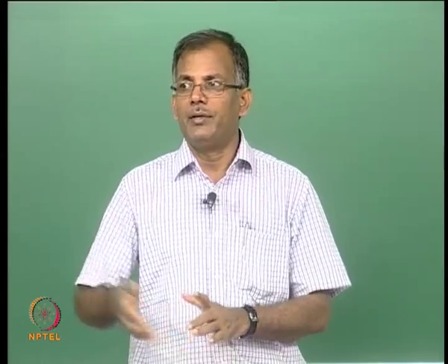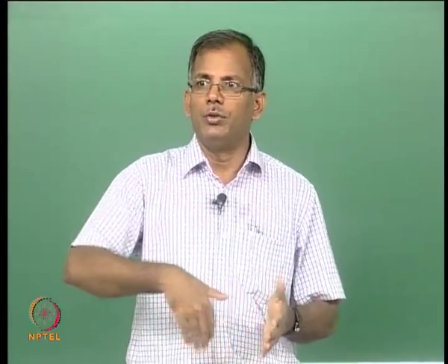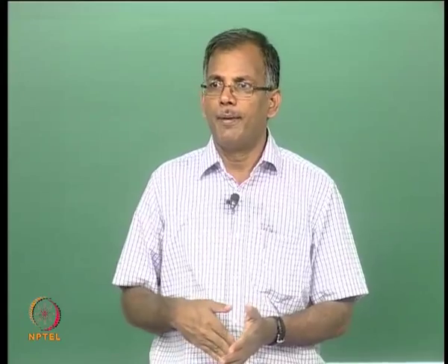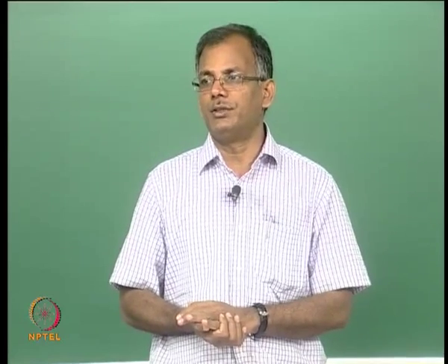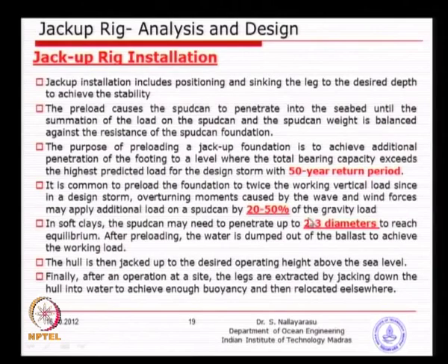So, that is where, when you have a small structure in the vicinity, I have shown you some photograph earlier on, that structure looks so tiny compared to the jackup itself. You will be disturbing the soil in the vicinity of the existing structure to such an extent that the existing structure might become very unstable. So, that is where you have to be a little bit cautious. Taking any jackup near an existing structure, a thorough study and investigation is required, not only on the safety of the jackup, but also on the safety of the existing jacket structure.